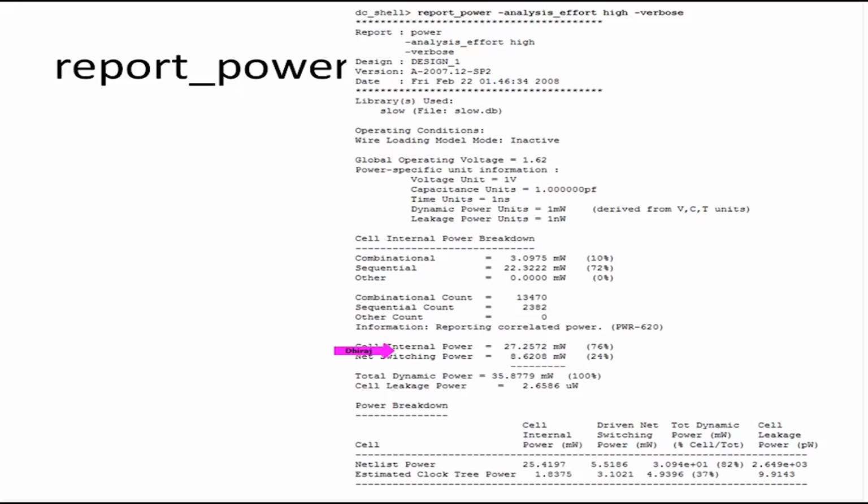This tells us it is probably a report just after synthesis. Obviously, the number of nets in a pre-layout gate level design is much less. The real capacitance will only come after layout. So the switching power would increase in most cases after the layout is done.